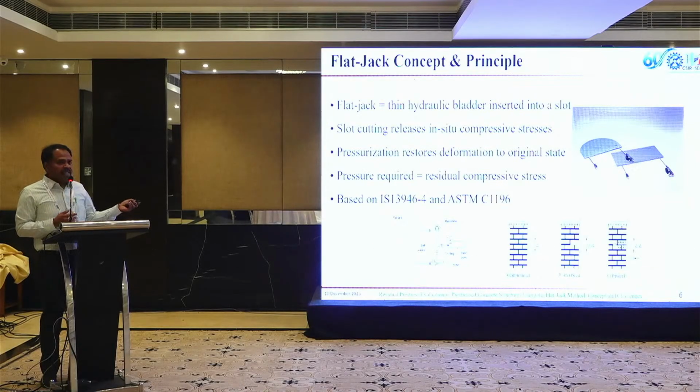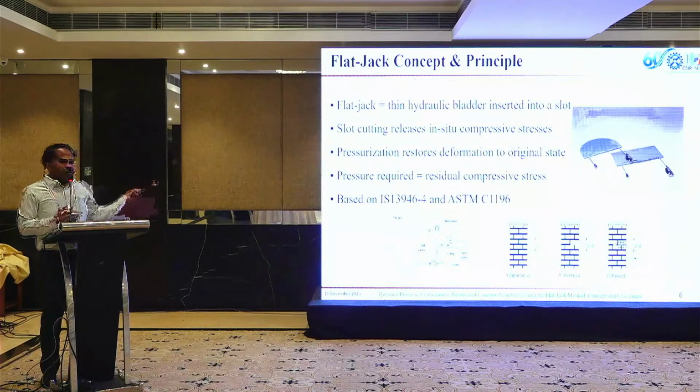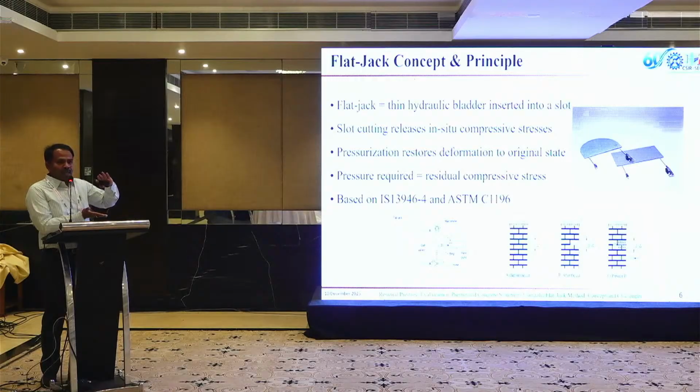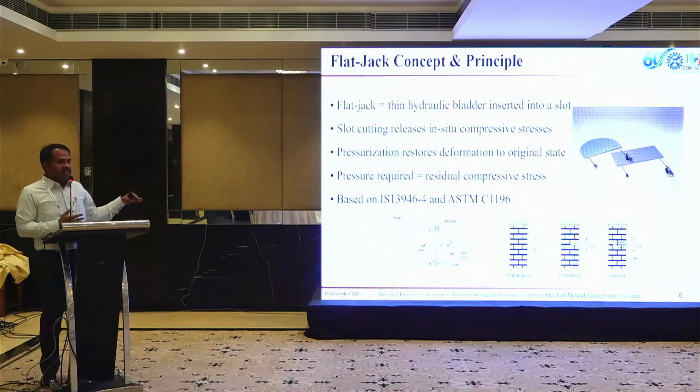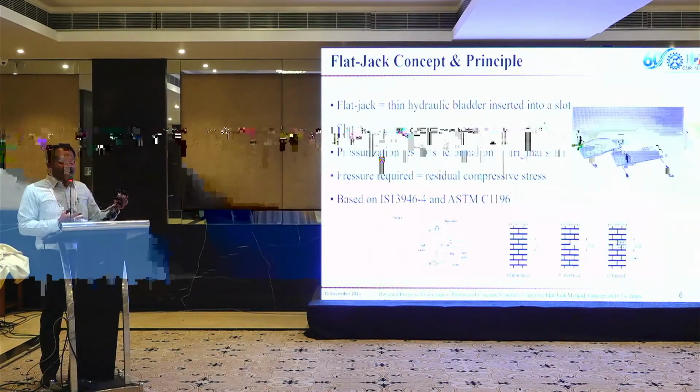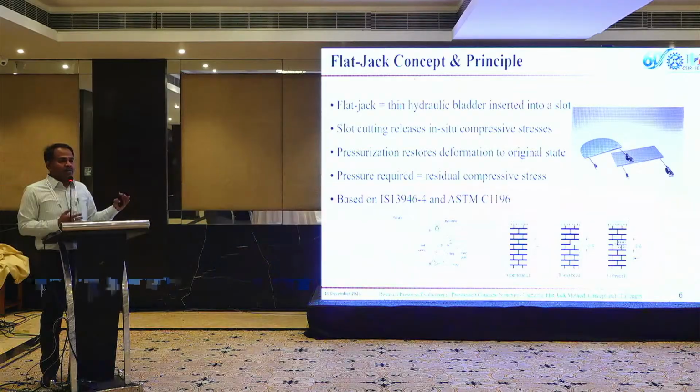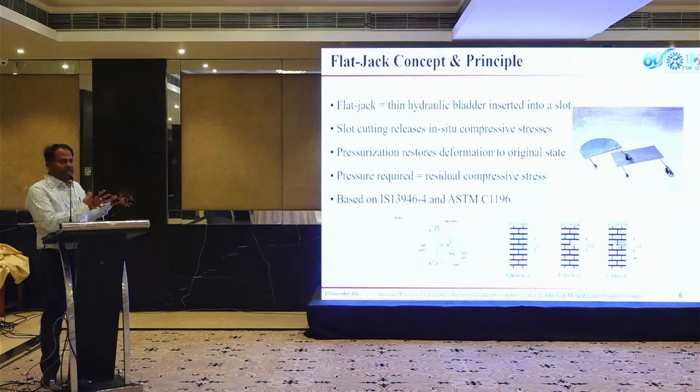It is a very simple bladder. What it does is make a slot in the model. Once the slot is made, the compressive stress will try to compress that slot. So the deformation before and after the cut is measured, and we insert this flat jack bladder to restore the original deformation, to see what is the pressure that is applied on the structure. So there is a relation between this applied